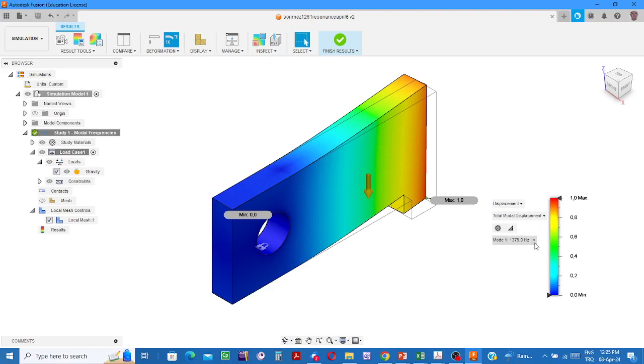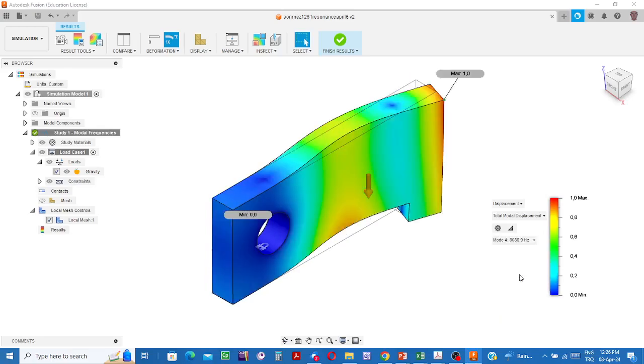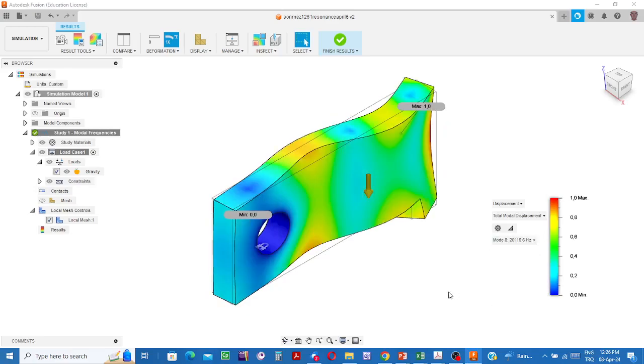Well, how many frequencies do we have? In the default configuration of the software, 8 frequencies are generated. Resonance frequencies: if the frequency of the dynamic load is equal to that much, then resonance will occur. While it is resonating, the body will fluctuate like this. If the resonance frequency is this one, you see fluctuations are different. Now, to be able to prevent resonance, this means the frequency of the dynamic load must be different from those resonance frequencies.